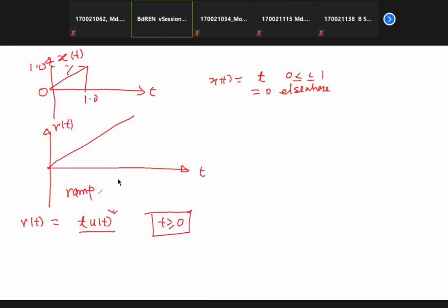Ramp means a vertical slope, okay, slope signal. Now, why do we need this? If someone writes this, they need not write it, okay? But if someone writes, for example, without using this u(t) here, then this becomes undefined, because then this portion of the straight line can be taken into consideration there. For this reason, either you have to multiply it with u(t) or you have to explicitly define it in your time, okay? So we are using this to define our ramp.